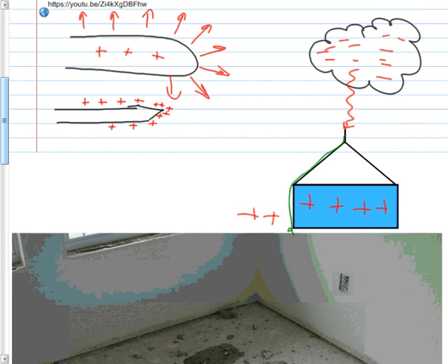Let's imagine this positively charged house. Well, those charges will tend to accumulate in excess on this point. And if this is attracting those positives, they will begin to bleed off that lightning rod. Now, if I lose the positive and it bleeds off, it begins to counteract the negative and it reduces the difference in charge. And it takes a big difference in charge for the lightning bolt to strike, to discharge. So if I can bleed off enough that the difference is reduced, lightning will not even strike. That is the second purpose of a lightning rod.